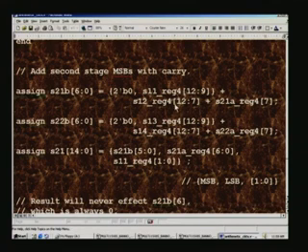We add 2 numbers, S11, S12, and similarly S13, S14 are there in the second stage for MSB, and so we need to add with the carry of the LSB, that is what is here, and so out come these results, and this will be the final sign bit.